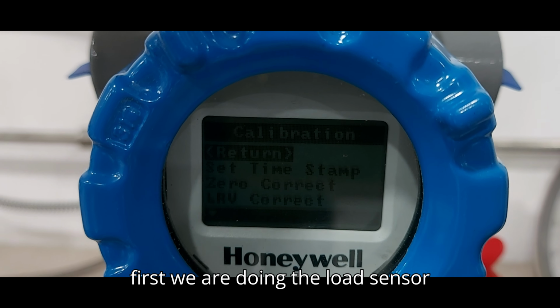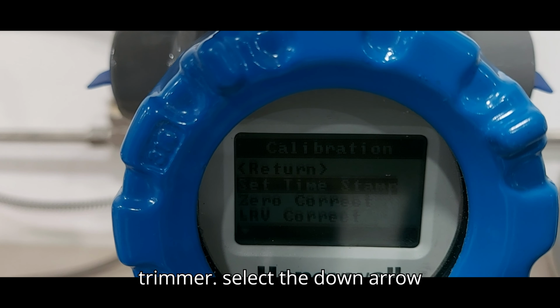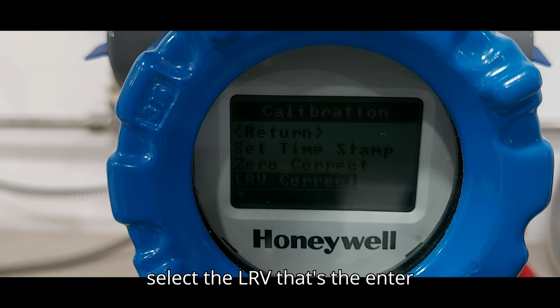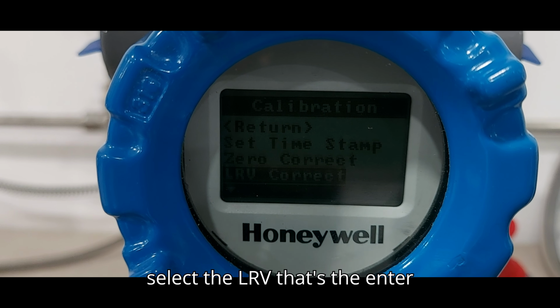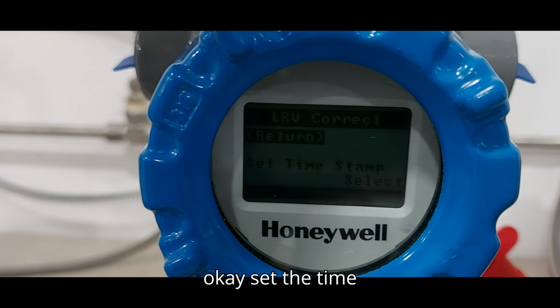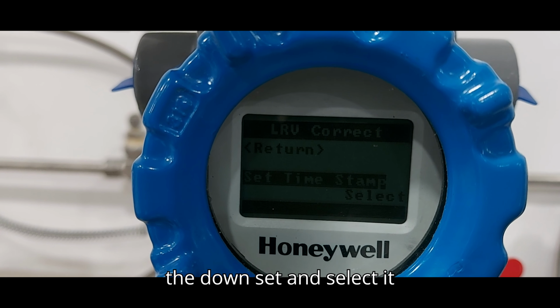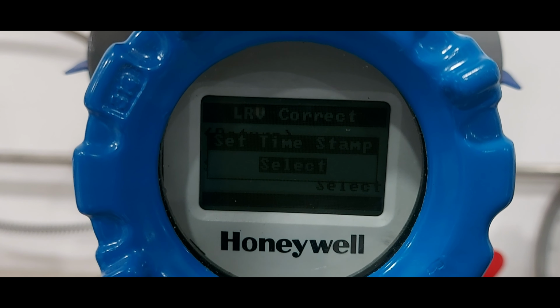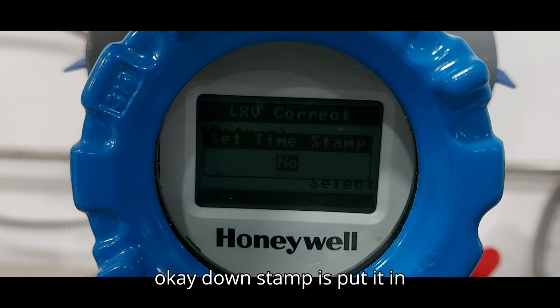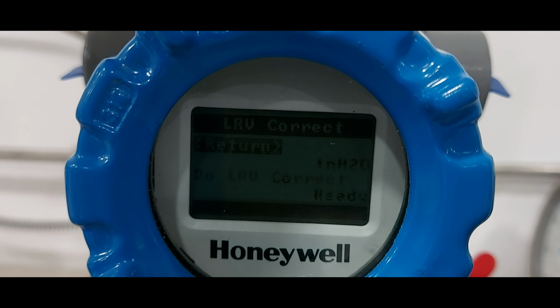Next we are doing the lower sensor trim. Select the down arrow, select the LRV, next enter. Set the time stamp. We are selecting the downside and select it. Time stamp is set to no, then press OK.